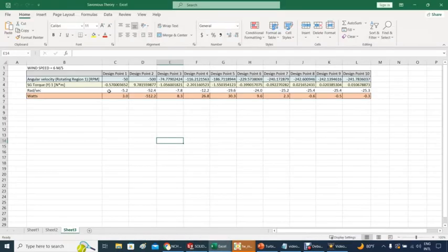There we go. So basically, at a wind speed of 6 meters per second, because that's the wind speed that I'm using, in miles per hour it will be about 13.6 miles an hour, kind of a breeze. And here are the results from the SolidWorks flow simulation at different RPM. And again, minus 50 and 500, you get these two values.